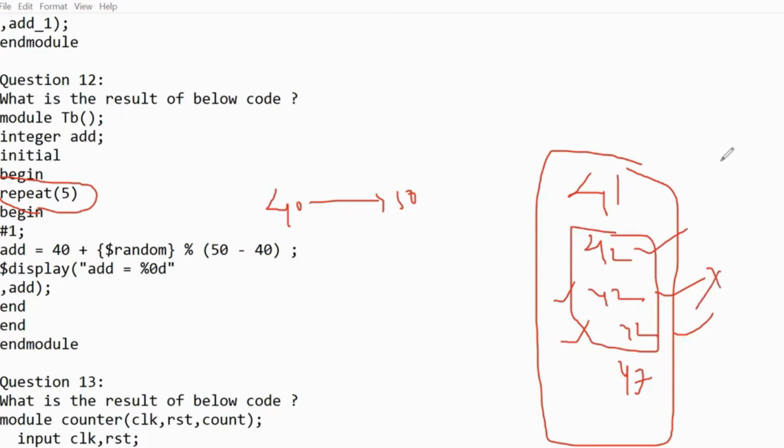If you go to SystemVerilog, when we are doing the randomization there, we can do it by putting the variable as rand. But this case we can avoid by simply using randc. randc is nothing but a cyclic manner. Once a value is generated, only after all the values have been generated will it generate the same value again. That's how we can avoid these things using randc in SystemVerilog.